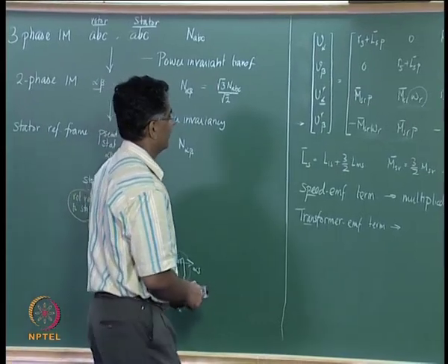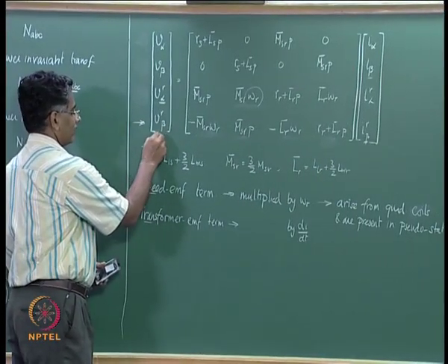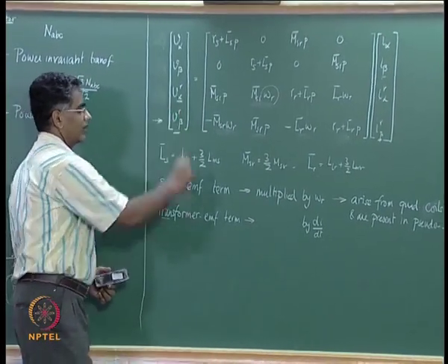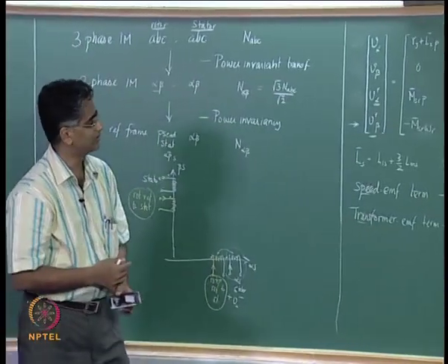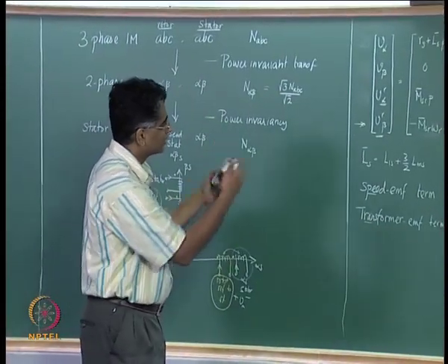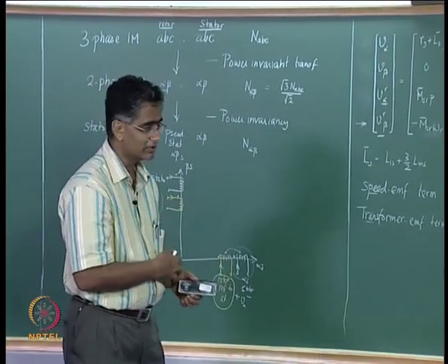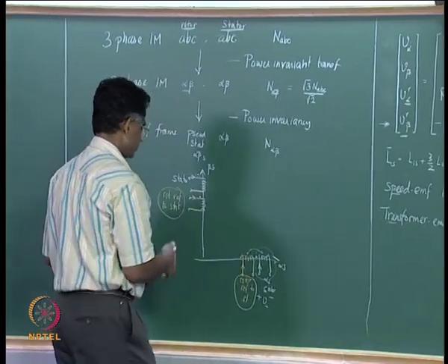And we also find that the speed EMF term is negative for all terms on this axis, not negative for terms on this axis. So, these are some of the observations that you make. This is how this appears to have been formed, and having understood this, one can extend this for more situations.